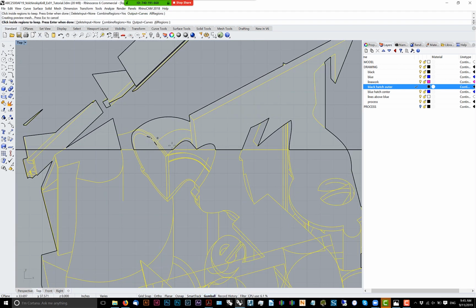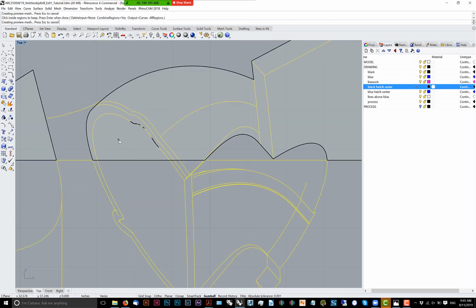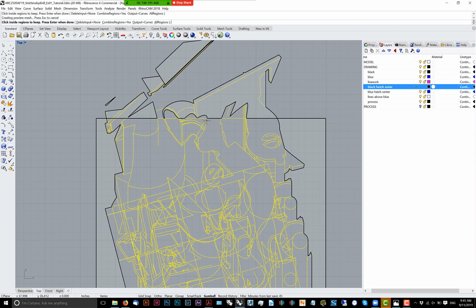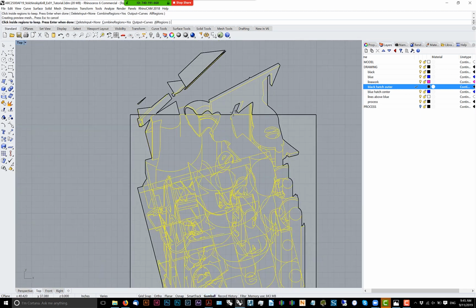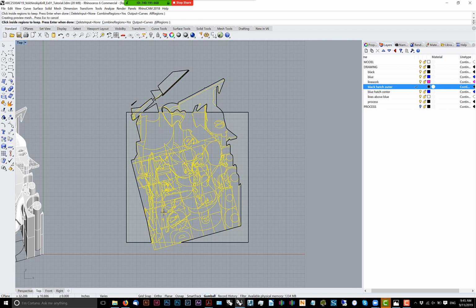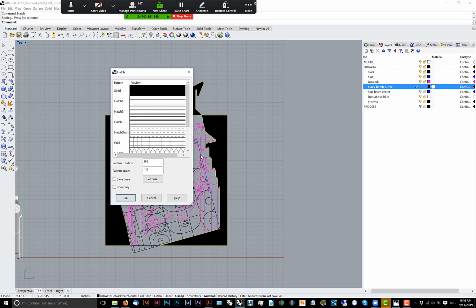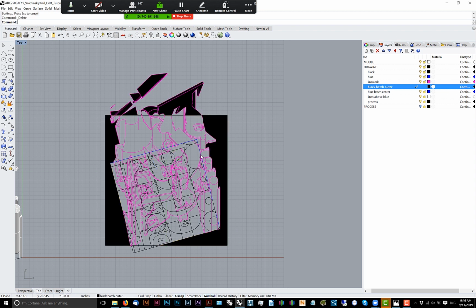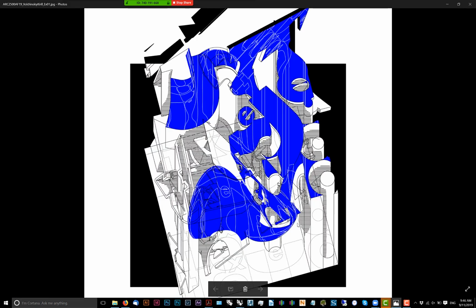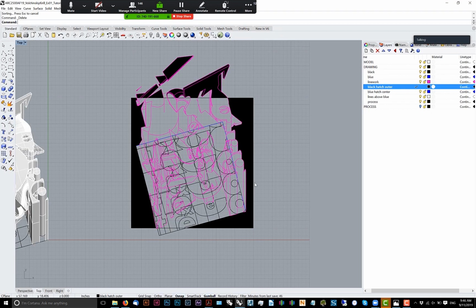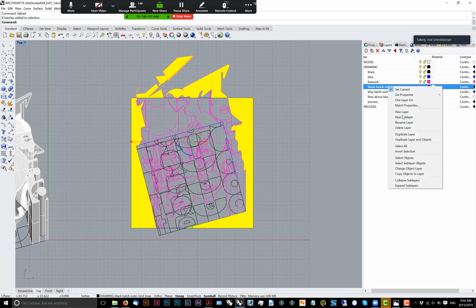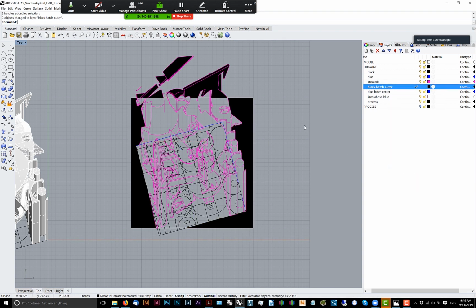And of course you need to do some graphical decision making to make sure that what you do is consistent with the look that you're trying to achieve. So now once you curve boolean around your line work, you'll hit enter, and you can run the hatch command to then produce that kind of outline boundary, like there, for example. So then you can use select last to then select your hatch and then copy it to a given layer.